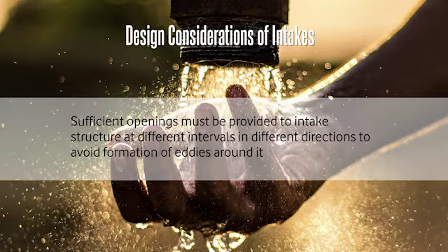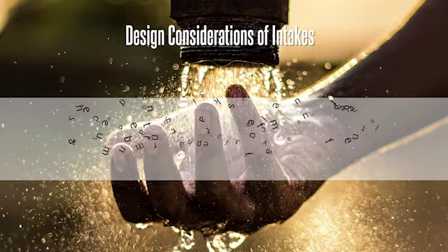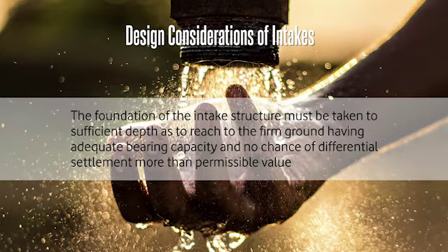Sufficient openings must be provided in the intake structure at different intervals in different directions to avoid formation of eddies around it. The foundation of the intake structure must be taken to sufficient depth as to reach firm ground, having adequate bearing capacity and no chance of differential settlement more than the permissible value.